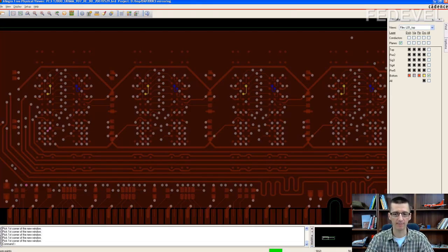Don't forget, place the via very close to the data pad, make a very short connection, the length has to be exactly the same on the top and on the bottom layer, and if it's needed, you need to do pin swapping on one of the memory chips.